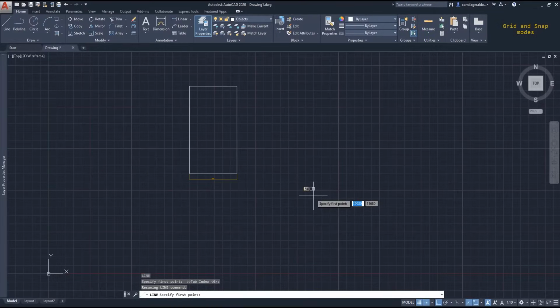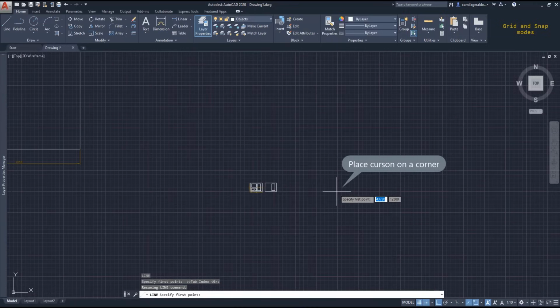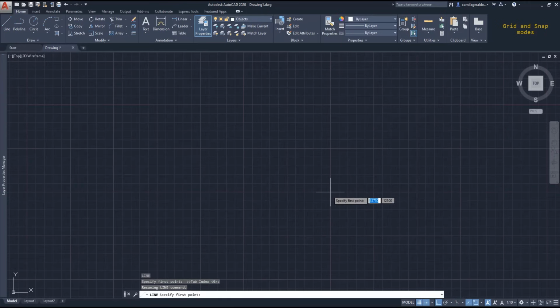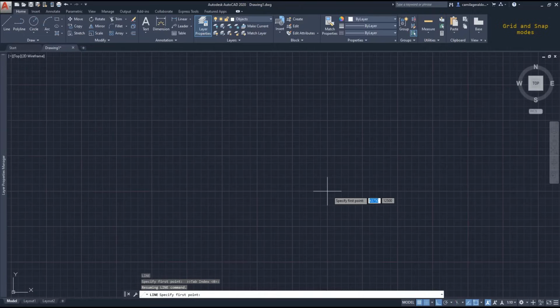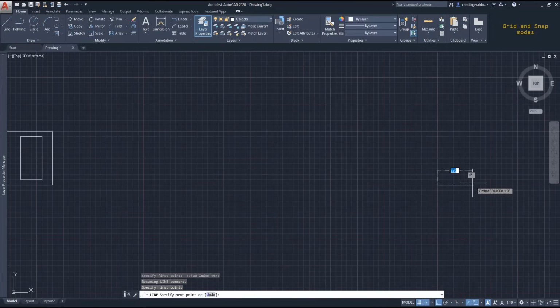If I like to have the workspace more organized and I want a point to be in the corner of an intersection when I zoom out a lot, like where I am now, simple. Place the cursor there, in the corner, and zoom in slowly, keeping the cursor in the same position. When the grid doesn't resize anymore, it means that the grid is now resized correctly.